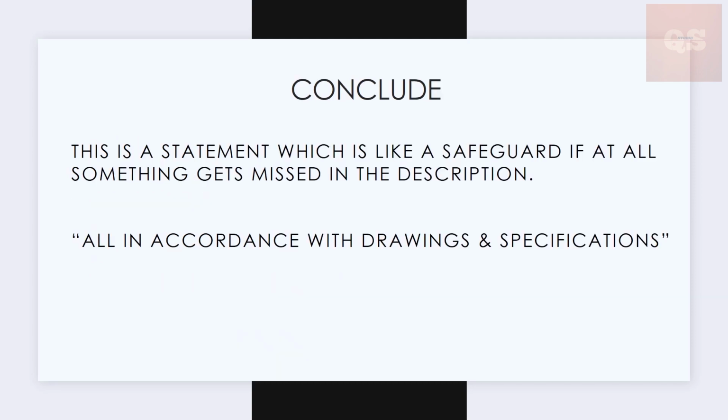And finally, we have the concluding statement. So this is just a statement which is like a safeguard if at all something gets missed in the description. So as a consultant, when you are building a BOQ, there are chances that you might miss something. So just to safeguard yourself, you are adding a statement which is like "all in accordance with drawings and specification." So if you see any BOQ, you will have this statement mentioned at the end.